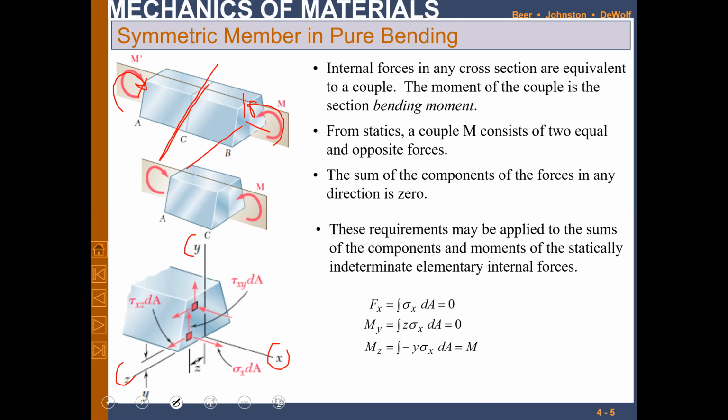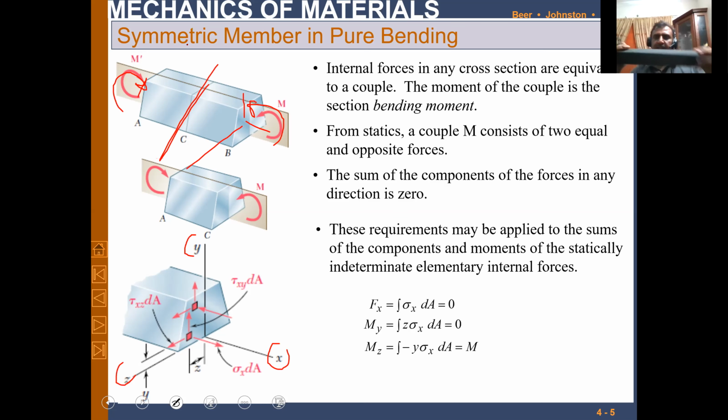We have already seen that whenever we apply bending into this one, now this is the Z bending, right? Z moment that is causing the bending, right? Upper part is going into compression, lower part is going into stretching or tensile loading, right? So neutral axis is neutral, no force is there, no shear stress is there, right?